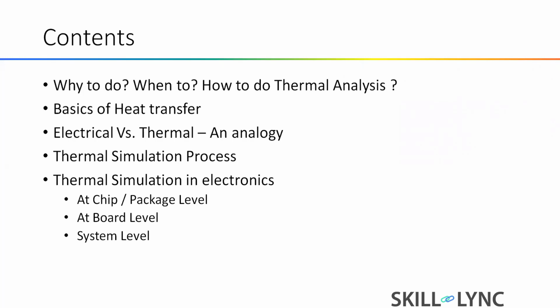In computational fluid dynamics, we have a certain process to follow. A similar process is there for doing the thermal analysis for electronics. The thermal analysis of electronics is purely based on the CFD process, but in CFD we have general CFD codes where we use different tools for different purposes. For the geometry, we have CAD software. For the pre-processing, we have CFX and Fluent. For meshing, we have different software. So in general CFD, we have different tools, but in electronics cooling, we have only ICEPAK, which is integrated. I'll take you through all the processes which we follow in the thermal analysis.